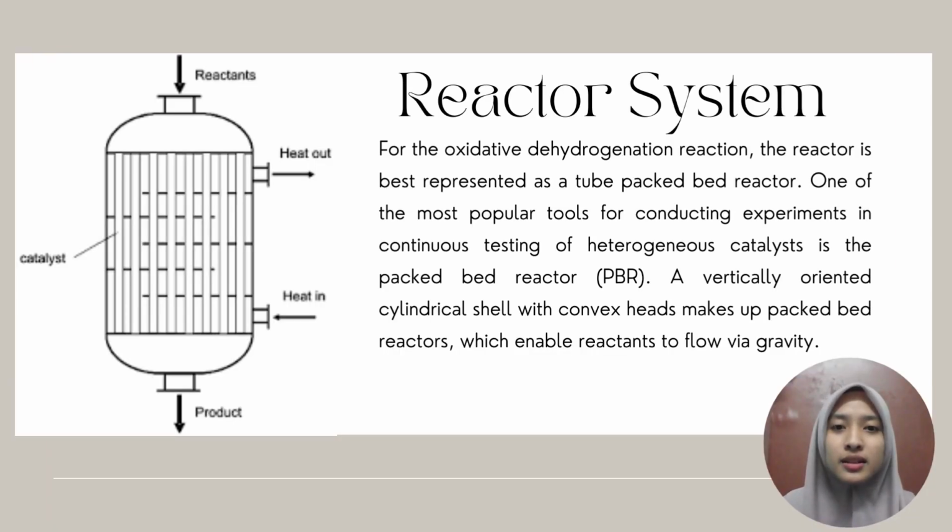For the reactor system, we choose to use packed bed reactor because it is good for oxidative dehydrogenation reaction and best for continuous testing of heterogeneous catalysts.